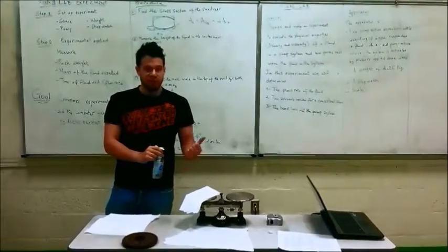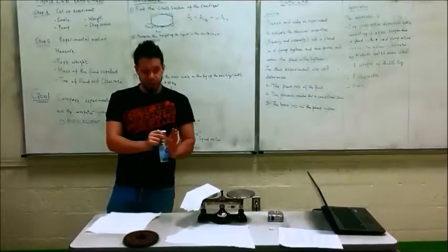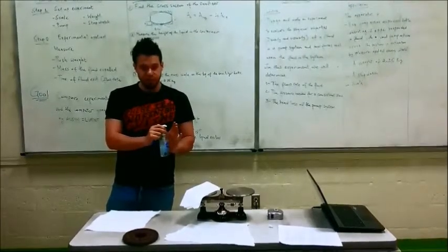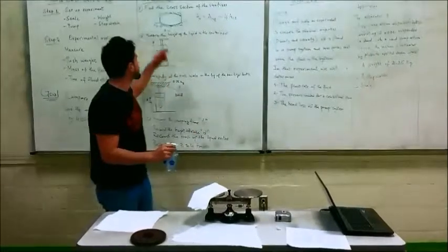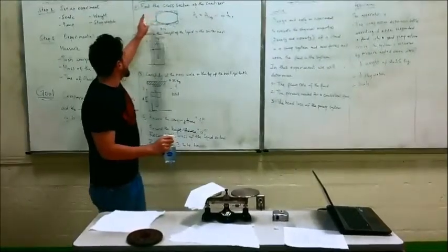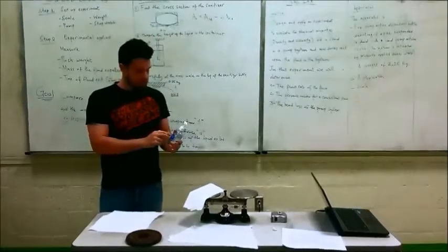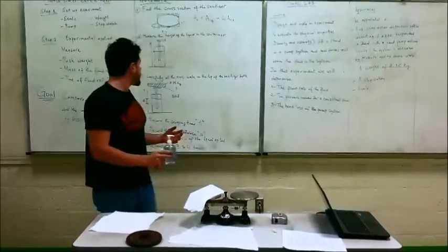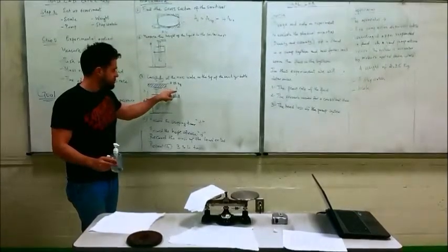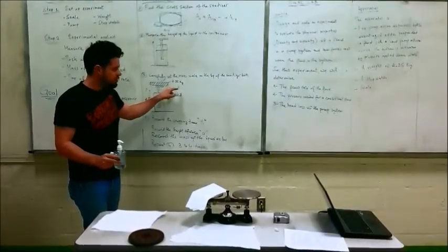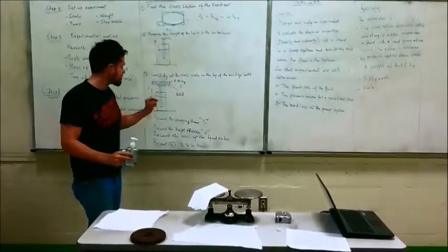We will have the density from the weight of the fluid expelled divided by the volume of the fluid expelled, which I just explained in part 1 and part 2. This will produce the density. Now we also will take the time of the fluid expelled. This will allow us, with the volume, to calculate the flow rate.